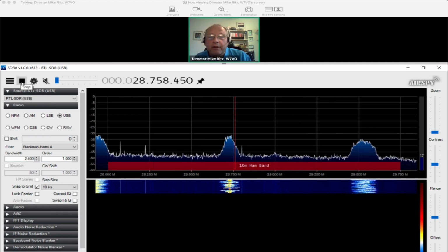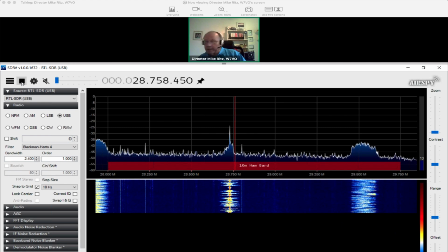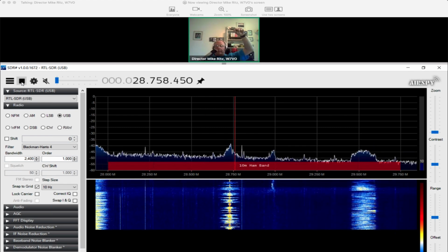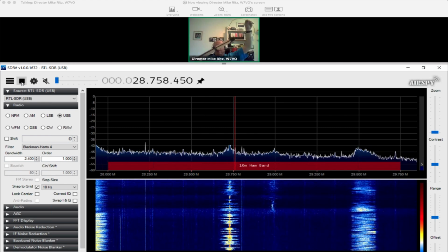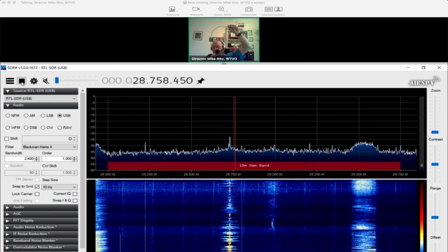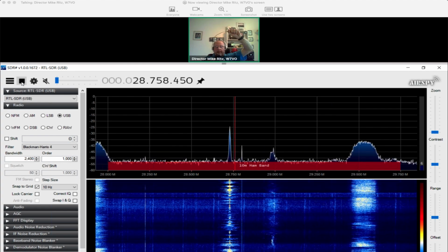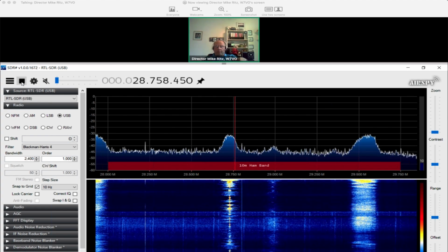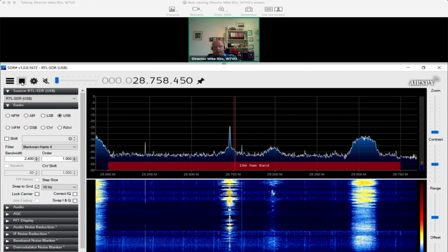And all of a sudden now you can see signals that are being picked up by this loop antenna. I don't know if you can see this antenna very well. Basically, it's a coat hanger on the end of a long stick, and I've got a common mode choke on it, and I can actually move this around the room, and you can kind of see the noise floor go up as I move this thing around.